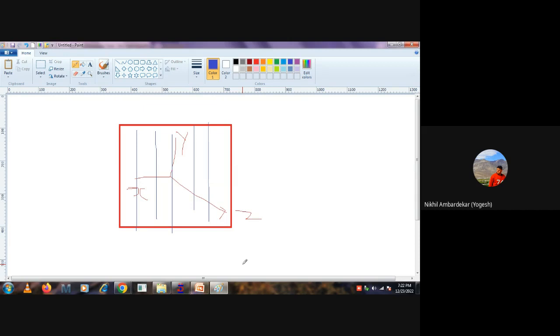So prepare your geometry, and once you come to the stage where you have to find out the moment, check its local axis, and based on that local axis note down your values, so you can design your rebars or reinforcement, correct? This is not constant, so these local axes will change because those are not global axes.